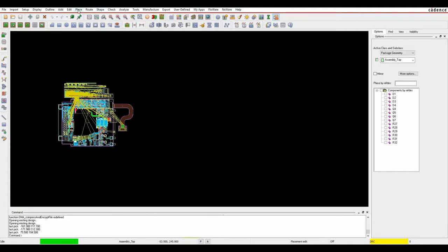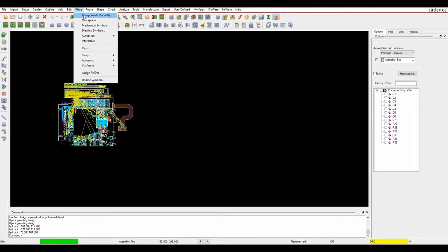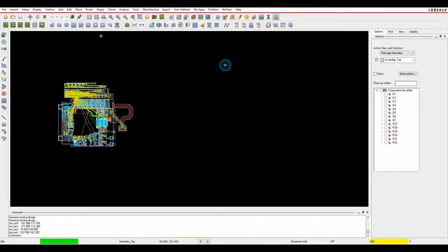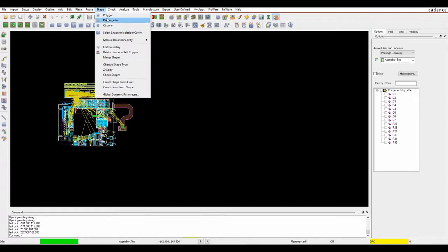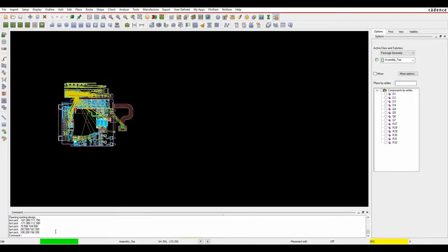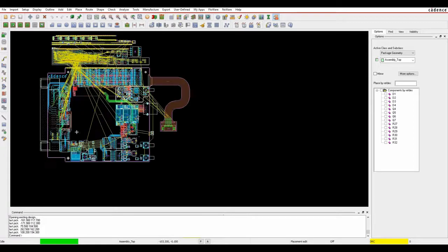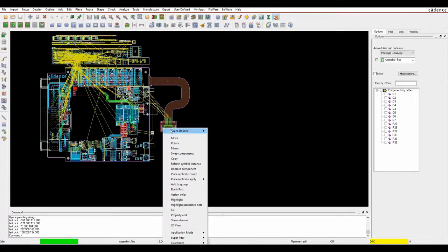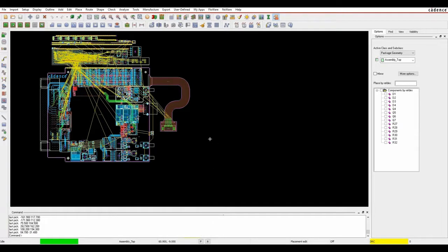So you can obviously choose a menu, choose a command that you wish to do, and then do something to the components. You can choose an icon, so the icons match the menu flow, so that's the typical option. We can assign shortcut keys or enter command line keys by typing them in. Or we can use the hover mode, so we can hover over what we want to affect and then right click and do things like move, rotate. So for a symbol, that would be different if we hovered over a track, for example.